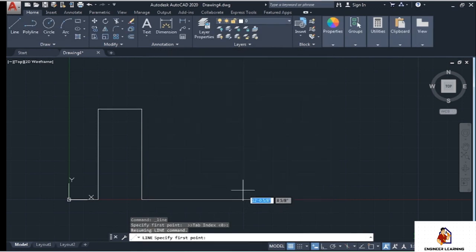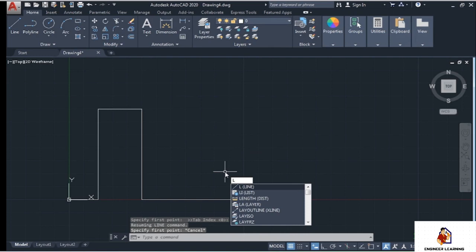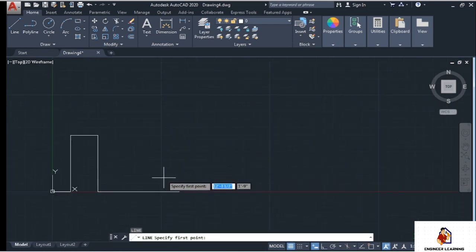Now with the help of dynamic tool, let's draw a line with certain angle. Activate the line tool with its command. Here you can see now the L input is entered near the cursor. We do not have to look down towards the command line to choose the tool. Press enter to activate it. First coordinate is always going to be absolute. So enter 30 feet, 0.